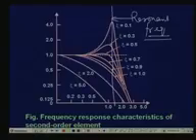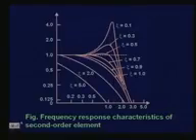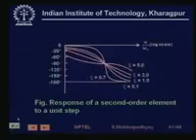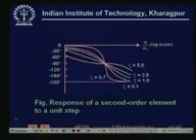You have similarly the phase. If you see the phase, the phase plot looks like this, again with frequency. Towards low frequency, the phase tends to stay small, and as frequency increases, the maximum phase that can occur is 180 degrees. So these are the phase lags.